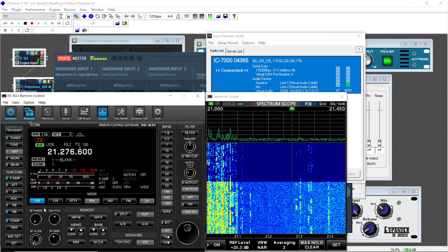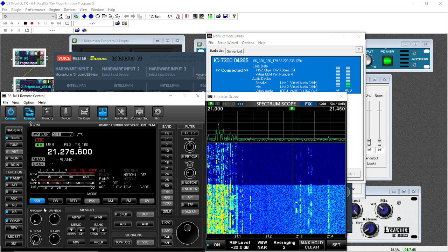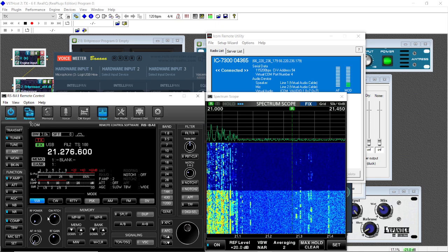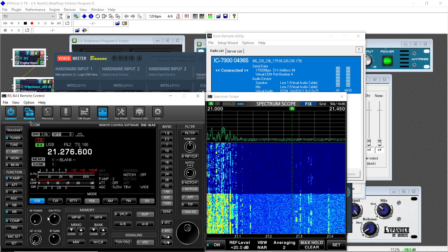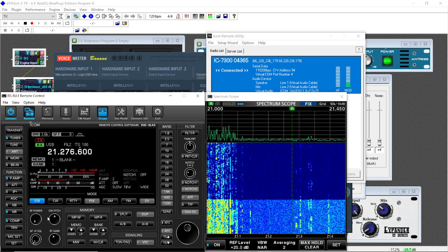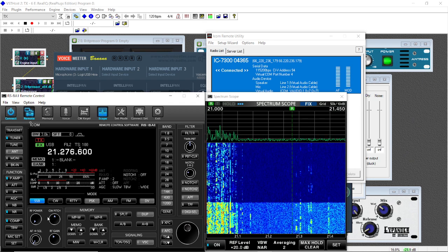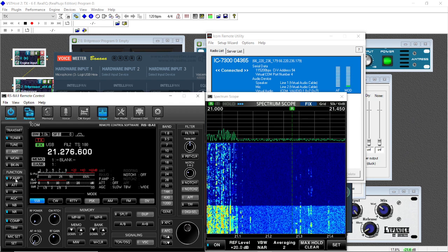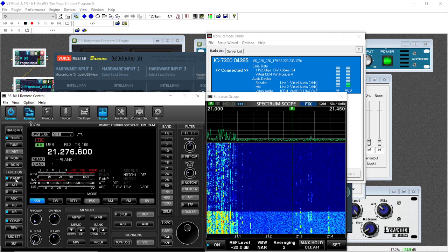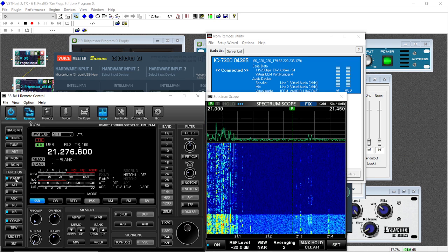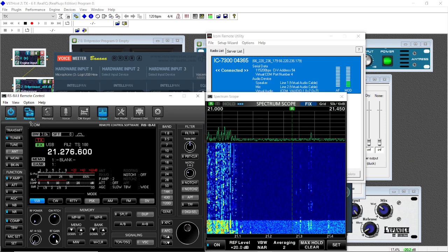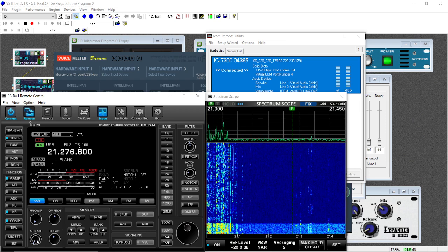Now, before I go into the other stuff, which is more complicated, I'm going to show you how to run this with the RxDAP. Trust me, don't do it any other way, and I'm referring to the ICOM. The RxDAP, you want to run both preamps on, preamp 2 on all the time on the ICOM. And you may think that sounds crazy, but it's not. You want preamp 2 on always, and the entire system is driven with the RF gain and the AF control.